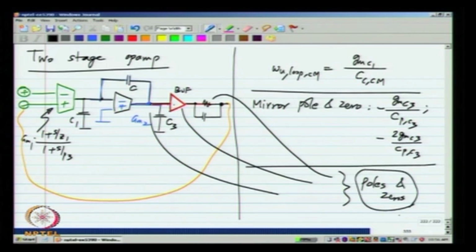So, there will be a number of poles and zeros. We have to make sure that the phase lag due to all of these poles and zeros at the unity loop gain frequency is, let us say, less than some value, so 30 degrees or so, so that you can have a healthy phase margin. Okay. Now, in practice, what you do is not to sit and calculate all of this analytically. You need to know which of the components contributes to poles and zeros, so that you can manipulate the values if you need to. Okay. If necessary, you can change the poles, that is, move the poles to higher frequencies and so on. But generally, once the circuit becomes so complicated, these hand calculations will not be efficient. So, we will go to a simulator.